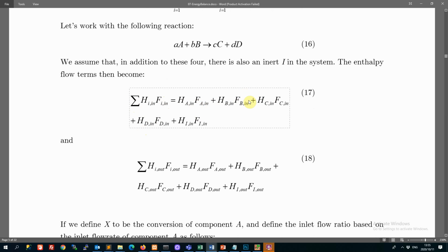And so you may still have A and B flowing, this is at the inlet point. So at the inlet point, you can have A and B coming in. And then we know C and D are products, but let's include them anyway. If we have no product coming in, then we can just set zeros for the molar flow rates here. Of course, we might have product coming in. I mean, if we have a recycle and if there isn't perfect separation and so on, it can easily be the case that we also have product coming into the reactor.